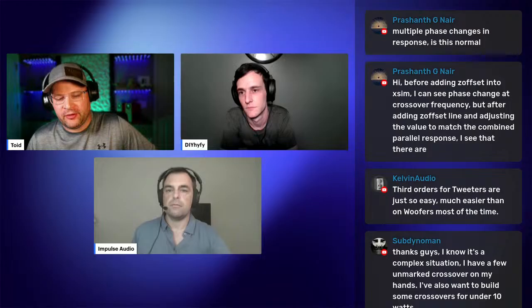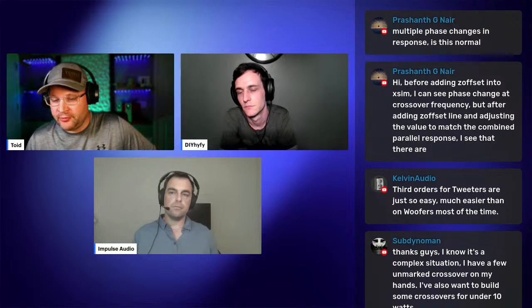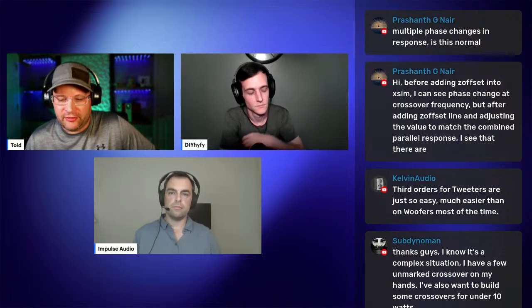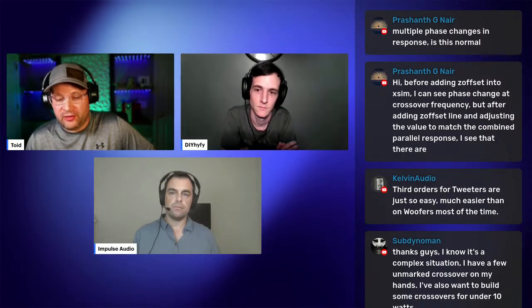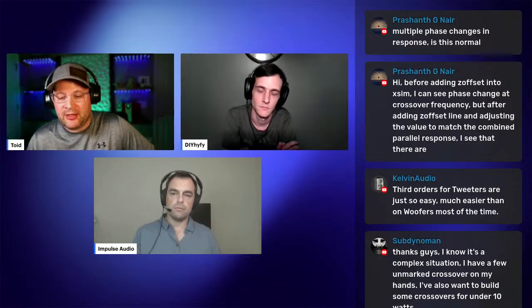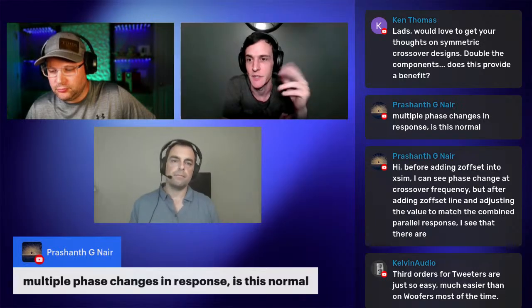Which is why a lot of people ask the same question, which I think is really important with crossover. You'll see the designers say on your tweeter, for example, and it really doesn't matter. If it's a two-way, it really doesn't matter if it's a tweeter or woofer that you change or midrange that you change. But they'll say reverse the polarity, or the positive goes to negative, the negative goes to positive. And they do that because of the phase response. Yeah. Which is totally natural. Someone asked, are those changes natural? And yes, those are just inherent problems when it comes to putting components in the signal path, which can be corrected either by higher order or equal order filters, or like Nick said, reversing the phase or the polarity of your driver to get them back into phase.